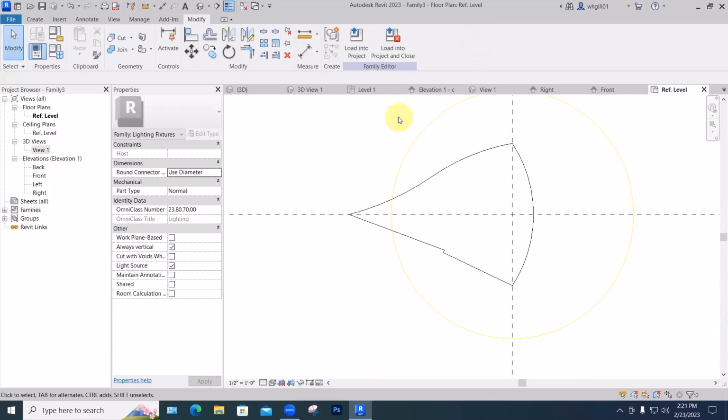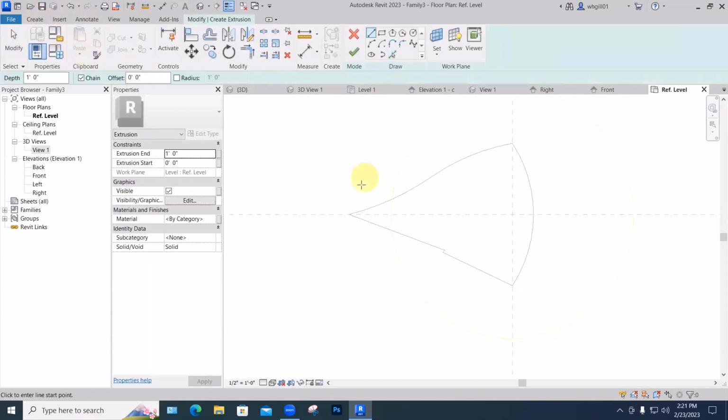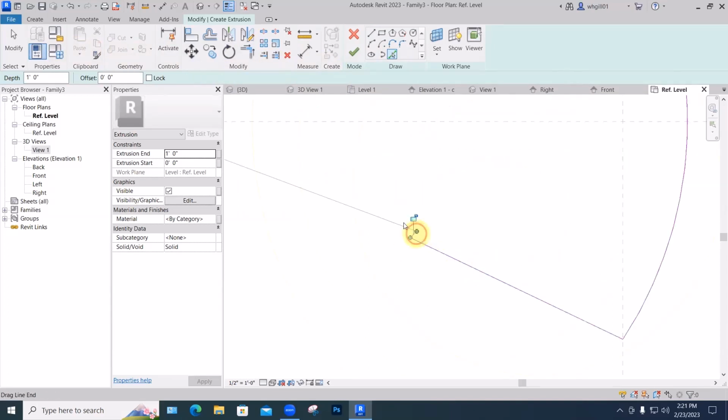Now, when we're making the walls, this will be an extrusion, but it'll be a 1 inch thick extrusion. Instead of trying to trace those, we can use this great tool, which just copies lines. So this green line and the pointer means as I'm creating my new geometry, I can just pick geometry that's there already, which is super.